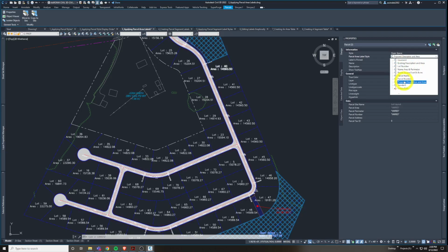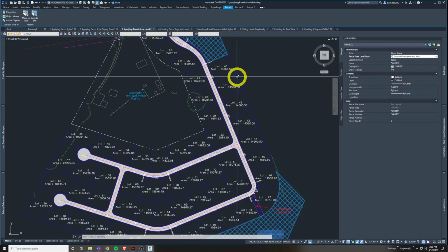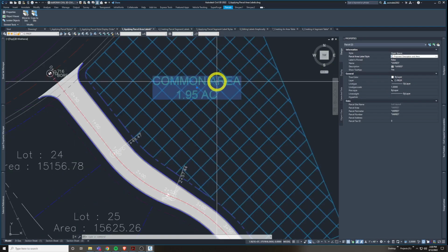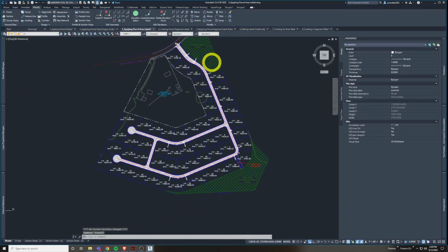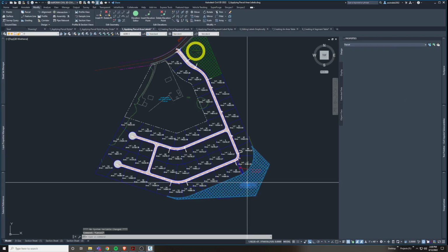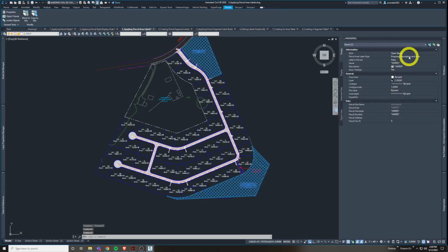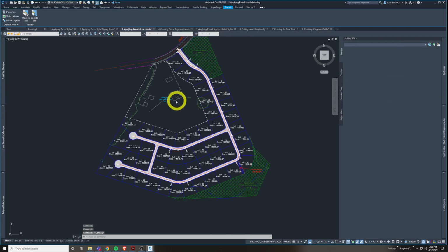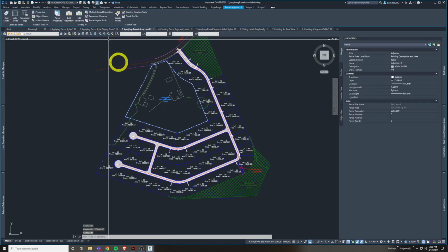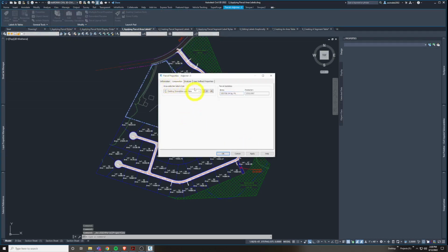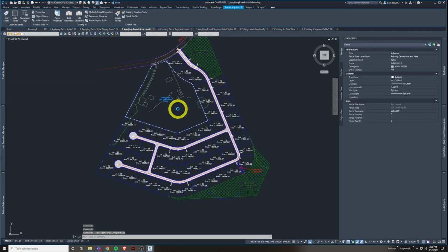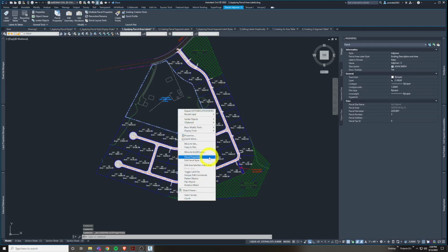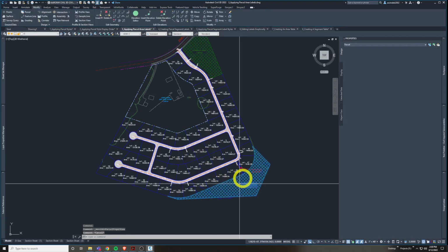This is another way to change multiple things at once. So I quickly changed these both all at the same time. I pre-selected them, then I changed the parcel area label style this other way that wasn't this way. If you have one thing selected, you can go here to its parcel properties, change it here, or right click and go here as well. Let's try it with two.